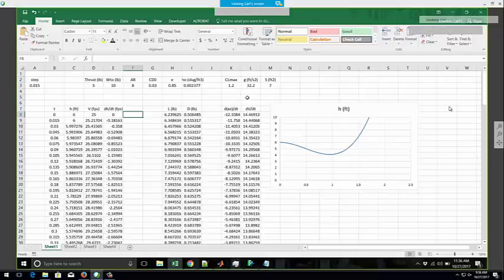It dips a little bit. It only dips a total of 6 inches over time, which is the x-axis. And that's at 30 feet per second. But if I go to 26, it's hitting the ground, right? 0 is the ground. You can imagine the ground. So your airplane can be extremely sensitive to this hand launch. That's something to keep in mind here. And then a way to model that is inside of this spreadsheet, which I added to the lab material back here as the electric HL.